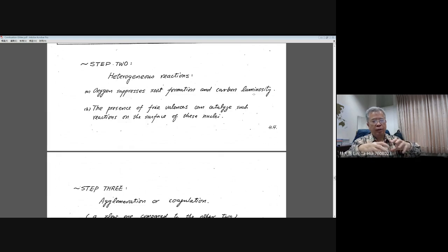Since even if you have a carbon, it is just like burning a coal particle. When you have coal burning, you always have a surface reaction on the coal surface. Similarly, for a carbon particle, there is a surface reaction between the carbon atom and the oxygen, and those oxygen will dig those carbon atoms out to produce carbon dioxide or carbon monoxide out of the coal particle and go into the gas phase, and we call this the so-called heterogeneous reactions.